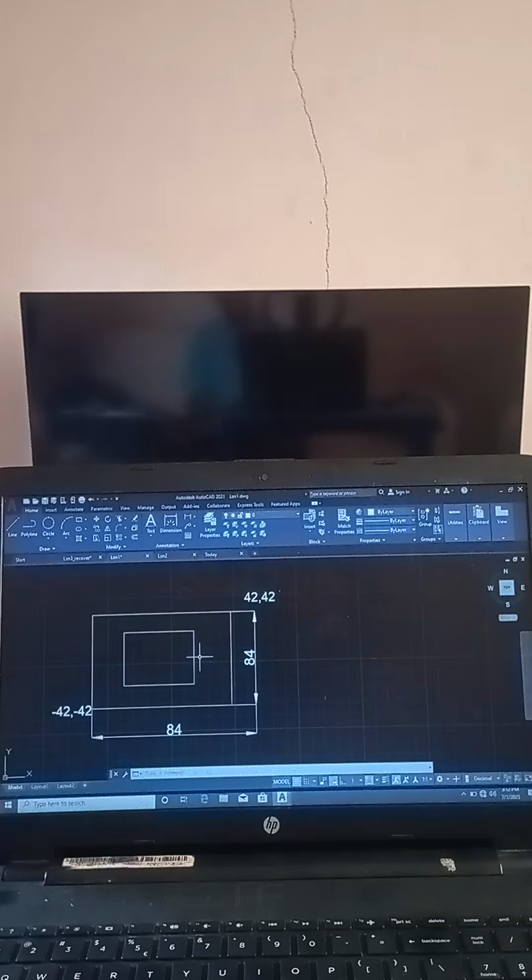All you need to do is make the limits in such a way that the beginning of the lower part and the end of the lower part, and the distance from the bottom part to the top, will enter the value of the drawn object. That's just the idea. Like now you have minus 42, minus 42 at the lower left corner, and 42, 42 at the top corner, as you can see in figure 1.12 on page 17. Very easy. The limit there is okay.